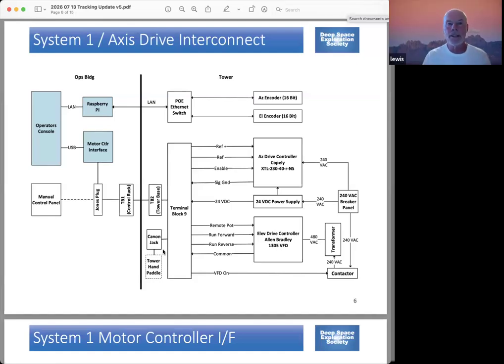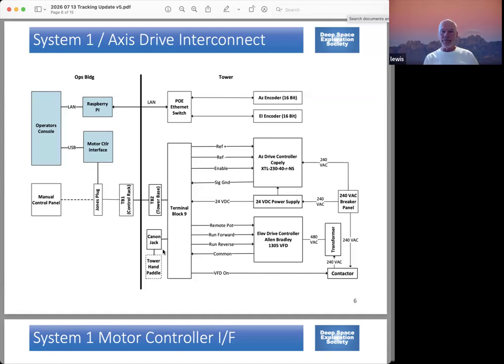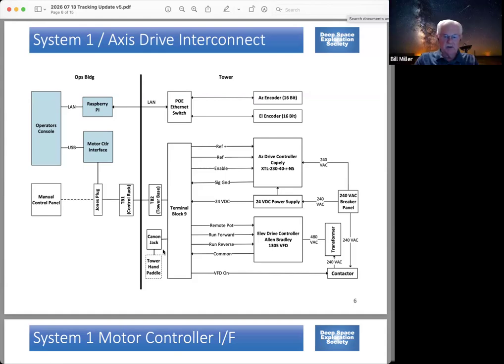There was a little power supply up there that gave it the plus and minus 15 volts that it needed, and that had failed catastrophically, so the manual control block that you could run out of the tower is no longer functional, and that used a round connector as well. It was a mini pin round connector, but we could always interface the joystick into a Jones plug interface and have that as an option down on the ground.